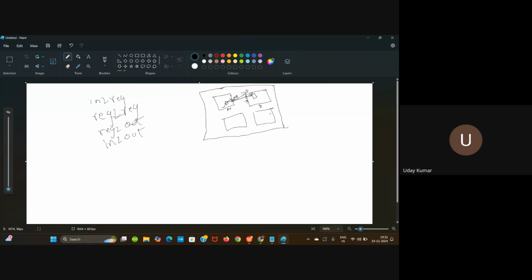Let us say there is another register here, and there is another register here. The best way to connect these two is taking this signal through this block to this block, the shortest distance, right? So these are called feed through ports.